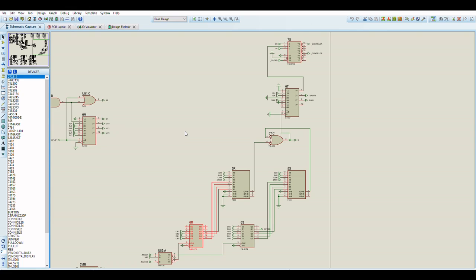So what it did on the horizontal schedule for the raster line schedule, there was logic that said, I want to be rendering 32 by 32 sprites right now instead of 16 by 16, and there was a little bit of subtle modification of the values that were used from the clocked inputs for the X and Y position, and also the palette index, and also the sprite index to be used.